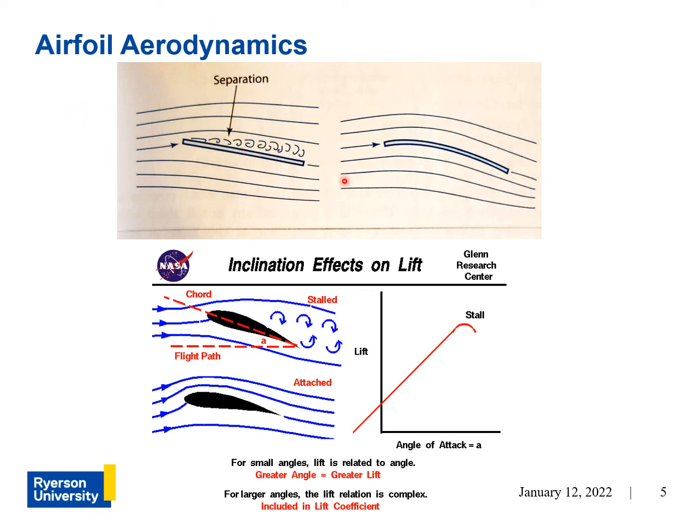And here, you'll start to appreciate the importance of camber or curvature. So curving the airfoil, aka adding a camber, delays the occurrence of flow separation, resulting in an increase in allowable lift and drag because the stall hasn't occurred at that angle of attack. And if it isn't evident, you can see that both plates are actually at the same angle of attack, but because this one has a camber, flow separation hasn't occurred yet.